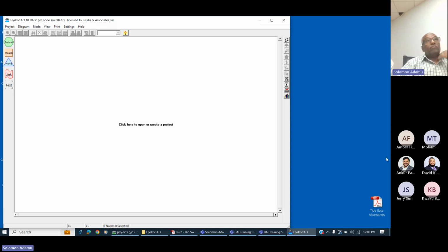I'd like to speak a little bit overall about what HydroCAD does. HydroCAD does water resources analysis independently. We don't need any other software to get data from. For example, for TR20, we need TR55 to get a curve number and time of concentration so that we can put them in TR20. That was our software before HydroCAD came in. So they need to go hand in hand, TR20 and TR55. But HydroCAD creates time of concentration and curve numbers itself, and does not need help from other software.